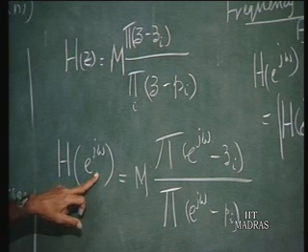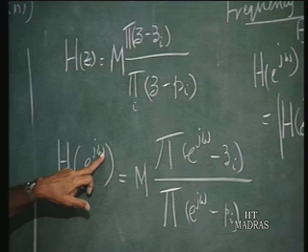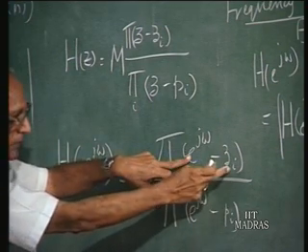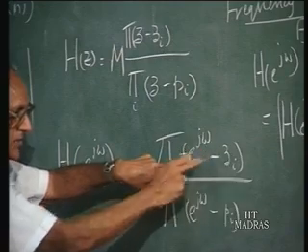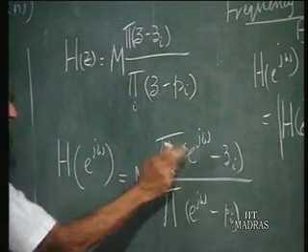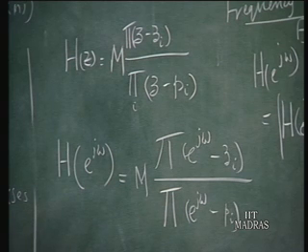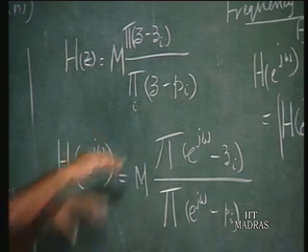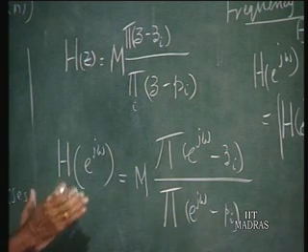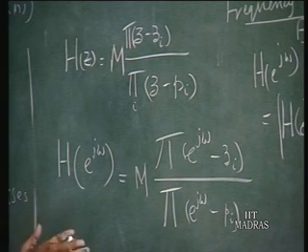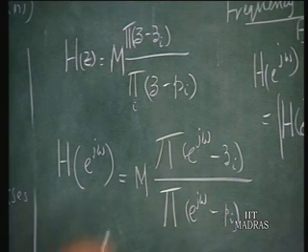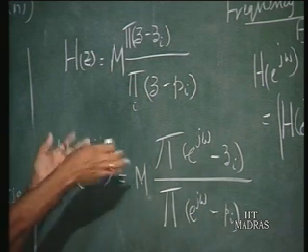So you take a point on the unit circle corresponding to the ω that you are considering. Each term represents the directed line from zi to the particular point under consideration. You take the product of all those complex factors, divide by similar products of the lines, complex numbers representing the line joining pi to e^{jω}, and multiply by the scale factor. That will give you the frequency response.